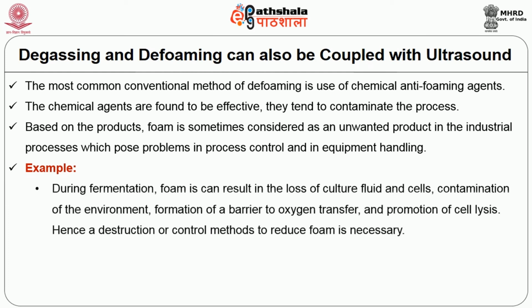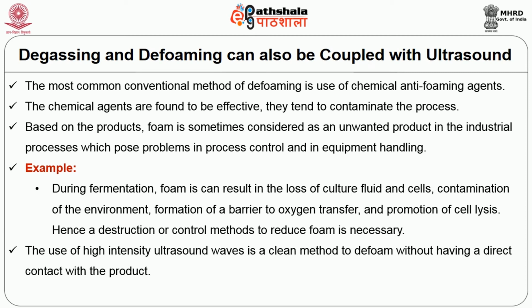For example, during fermentation, foam can result in the loss of culture fluid and cells, contamination of the environment, formation of a barrier to oxygen transfer, and promotion of cell lysis. Hence, a destruction or control methods to reduce foam is necessary. The use of high intensity ultrasound waves is a clean method to defoam without having a direct contact with the product.